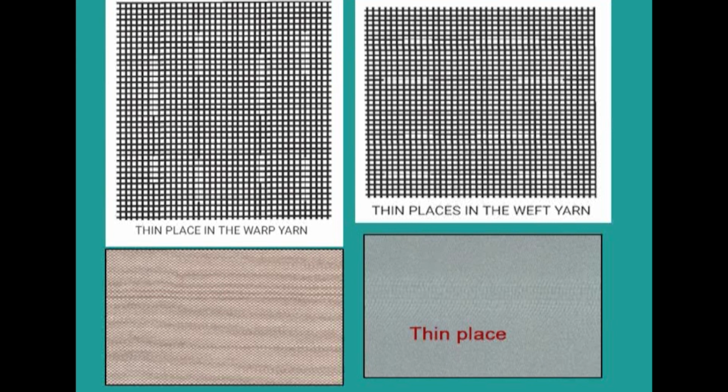And we have thick places. A thick place is a prominent band in which an increase in stitch density compared to the rest of the fabric is apparent, and sometimes it is taken as a minor one. And if you have thin places in the fabric, this is also called a defect, and it is often caused by the filling yarn breaking and the loom continuing to run until the operator notices the problem, and so it can be considered as a major.